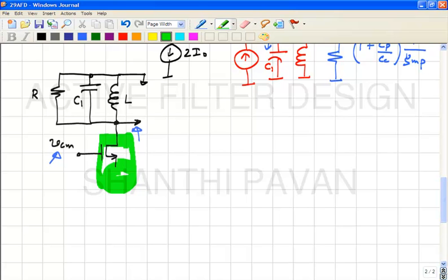Okay, every analog thing is simply differential pairs in various forms, and you should be very thorough with the operation of the differential pair. So technically, it seems as if we are safe, because even though there is an LCR network at the top, the amount of current exciting the LCR network is 0 because of the infinite output impedance of the current source. In practice, however, what are all the non-idealities you can expect with the current source?